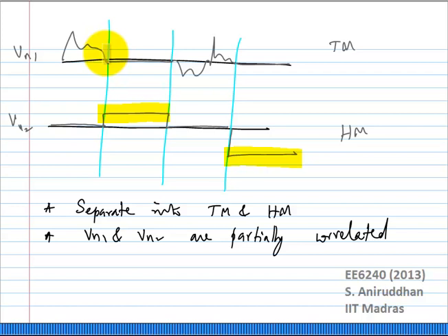Absolutely. So which is why you will have to consider two things. You will have to consider the noise from low frequencies versus noise from high frequencies. As he mentioned, if the RC bandwidth is very high, meaning the RC time constant is very small, the sampled value will discharge very fast, in which case you don't have to worry about that noise.